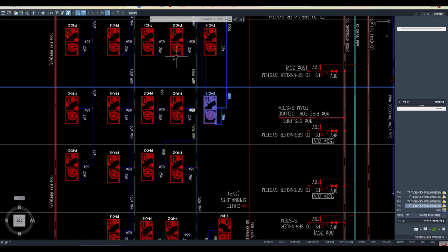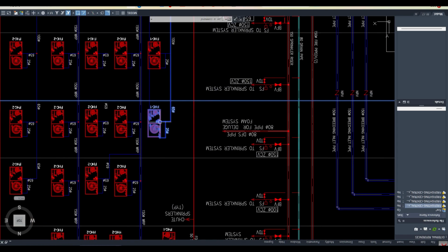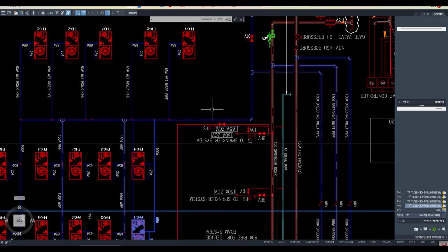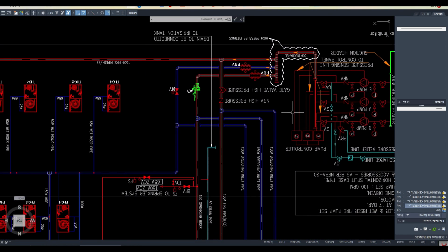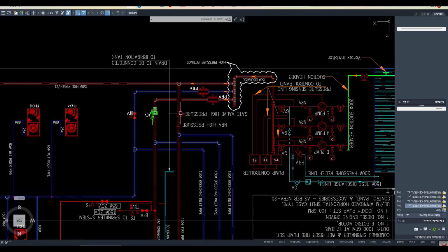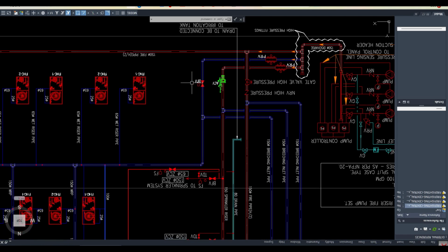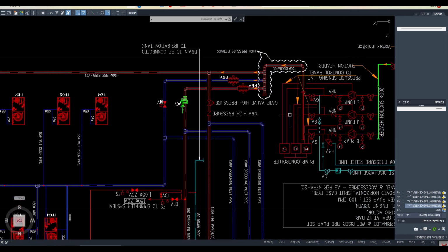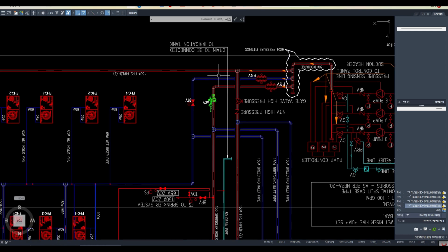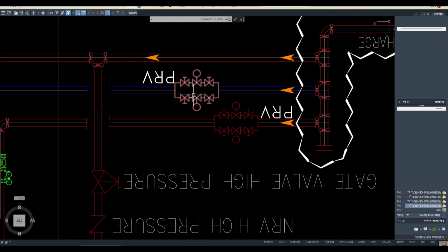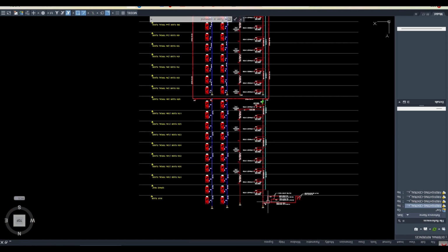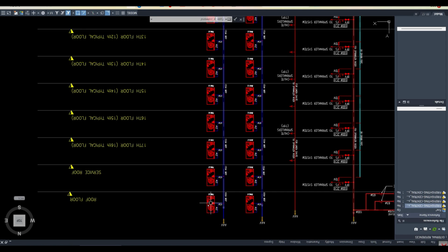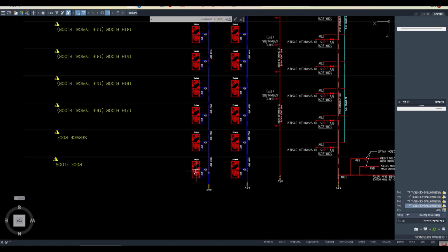So that is the rule of this fire hose cabinet. This system I explained already. I will maybe publish the video, and you can see it then. Most of you guys were not there, so basically I will just cover it from here. First of all, this pumping system is the same. From there it's coming, and this has the PRV system, maybe to deliver to the sprinkler at the end, or to deliver this pipe at the end, because we always consider pressure at the remotest place.